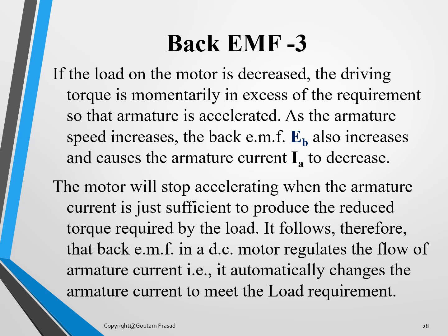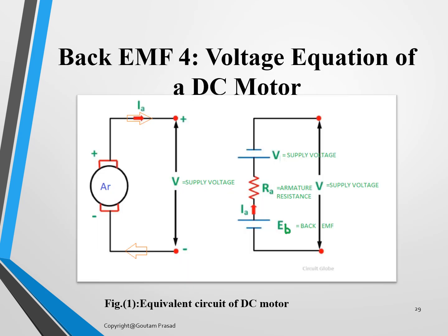The motor will stop accelerating when the armature current is just sufficient to produce the reduced torque required by the load. It follows, therefore, that the back EMF of the DC motor makes the DC motor self-regulating. Back EMF has been explained in a better manner in this slide.